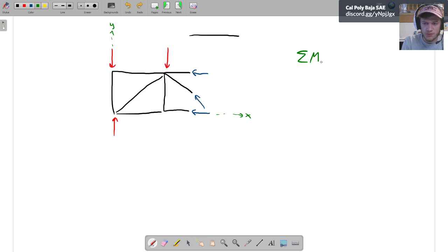We'll say the sum of moments about A equals 0. So we're no longer dealing with particles. So instead of just the 2 equations, sum of F_y equals 0 and sum of F_x equals 0, we now have a third one. So we have three equations we can use, 3 unknown forces. Because remember, we solved that one in the first step. This was our reaction at that slider.